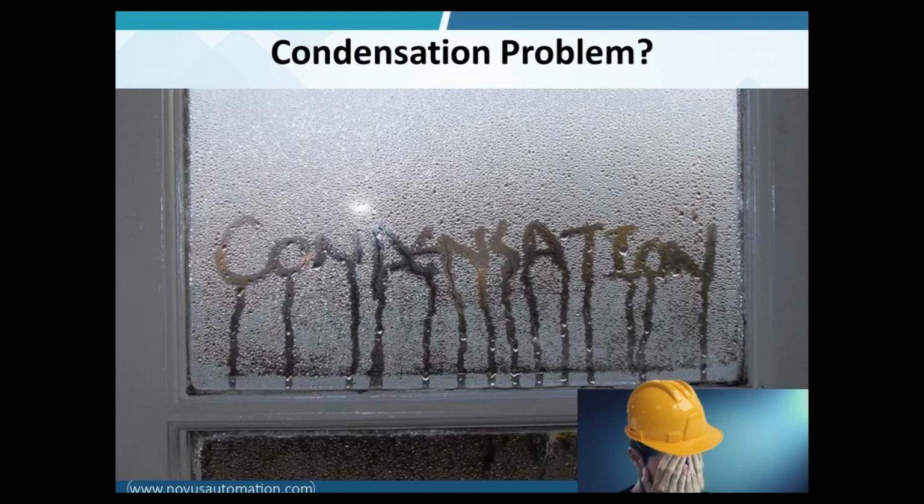In indoor climate control, the humidity affects both thermal comfort and indoor air quality, facilitating the growth of molds or bacteria, which can cause respiratory problems, and condensation forming on windows, walls, and ceilings that are colder than the air temperature, potentially damaging building materials. In drying processes of powder products for the chemical industry, for example, it provides better flow behavior and avoids formation of agglomerates.